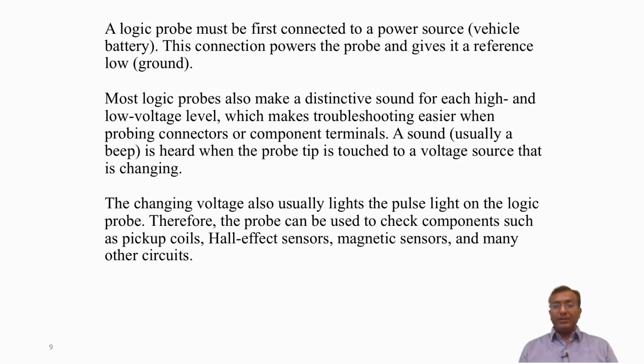Therefore, getting the summary of today's lecture, we all know that if we are performing troubleshooting for a particular vehicle, using an ammeter to measure starter current, a test light to check battery power, and a logic probe to check the relay signals can pinpoint the problem efficiently. I hope you have understood the significance of these test equipments. Use of proper test equipment at a proper location is very crucial.